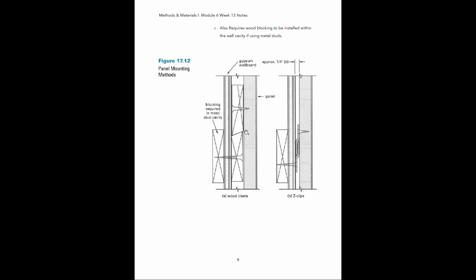And you can see the way that these are cut. They're cut at a slight angle. And being cut at this upward angle is going to prevent the wall panel from slipping and falling off the wall surface. So obviously if this was just cut at a perfect 90-degree angle flat and you set one on top of the other, there wouldn't really be anything locking this into place, so it'd be very easy for the panel to just fall off of the wall. So that's why they put this slight angle on the cleats.